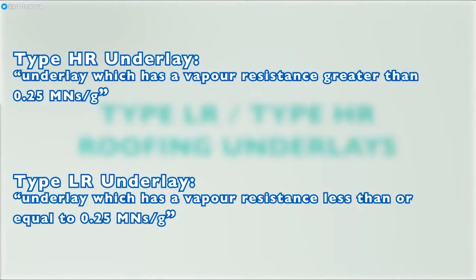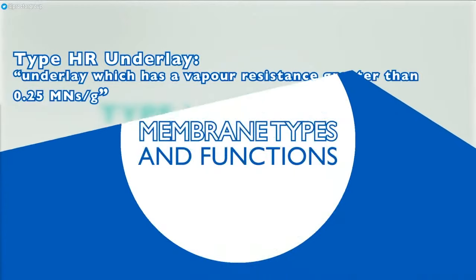LR membranes can be specified without roof ventilation if that application is covered by current third-party certification, while HR membranes will typically require ventilation in all circumstances. LR membranes, which are also air open, will typically have fewer restrictions and exemptions applied to non-ventilated use.